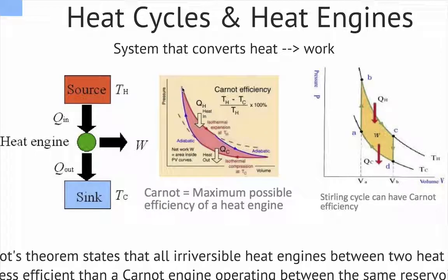So if you think about the cycle, this repeats over and over again. You notice something, that it is not going back in the same cycle, right? Going down is in this curve and going back is in this curve. And the difference between these two curves is equal to the work done by the system. And this is an important concept. So the net work is the area inside the pressure volume curves. So you really want to maximize that area when you start thinking along this for these curves.